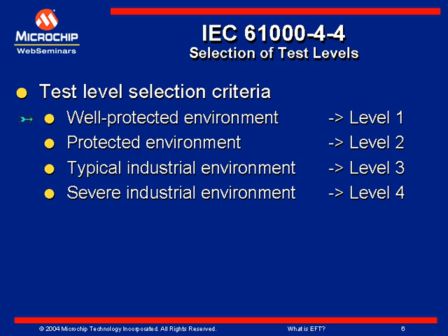The installation is characterized by the following attributes: a suppression of all EFT bursts in the switched power supply and control circuits. There is a separation between power supply lines, AC and DC, and control and measurement circuits coming from other environments belonging to high severity levels. There are shielded power supply cables with the screens earthed at both ends. Maybe the computer room may be representative of this environment.